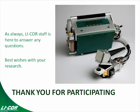All right, Pat, our first question is, how bad do the marks on the hose barb need to be before I must replace it? Basically any marks that you can see on the hose barb are going to cause a leak around the tube and hose barb interface. And the bigger the mark, the bigger the leak. But we recommend if you can see a mark at all on that hose barb, go ahead and replace it. They're fairly easy to replace, and they're inexpensive, and it's going to give you much better measurements.